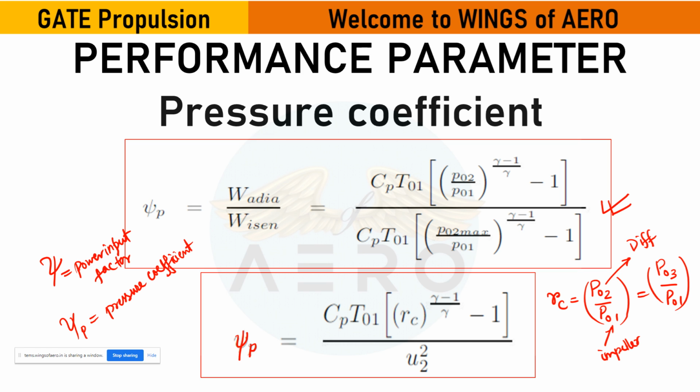It is a slight difference with efficiency, because when we take efficiency, we are considering both the ideal case and the adiabatic case as the same. When we write this formula, P02 by P01, we write T02 prime by T01. We are not using prime, where prime means isentropic and without prime means adiabatic conditions.